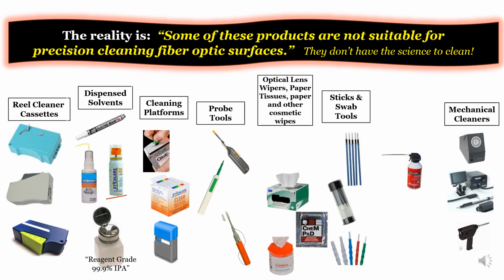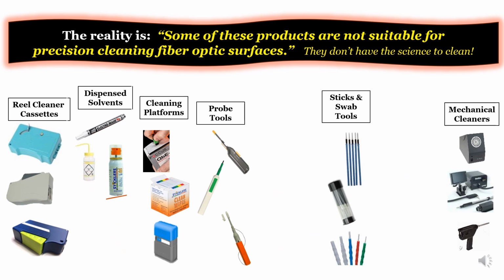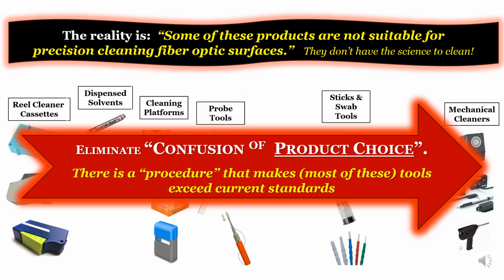And then finally, solvent selection. Isopropyl alcohol is still commonly used. Isopropyl alcohol is fine for fusion splice prep, but the solvent itself isn't capable to remove the different types of debris that may be encountered in the fiber optic deployment. Remember, what we're looking for is open architecture, something that's universal, something that creates a common denominator, and isopropyl alcohol simply isn't that solvent.